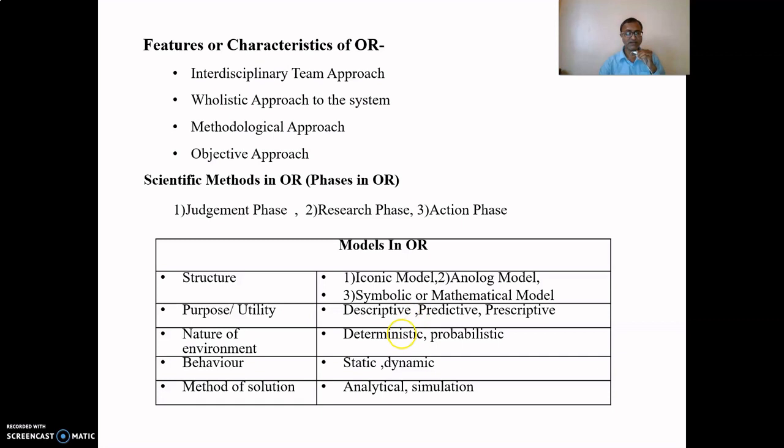predictive model. Another is the prospective model. Once you know that the results are going to be achieved correctly or 100% true, then you can adopt that method. Suppose you do certain operations and get a certain finish, say 1 micron or 2 micron, by using a different combination of variables, that is cutting speed, feed and depth of cut, and the material, the machine, and the skill of the worker. If the same or similar type of jobs or works comes up, then we can use the similar earlier variables to get the work done. So this is probabilistic in nature.